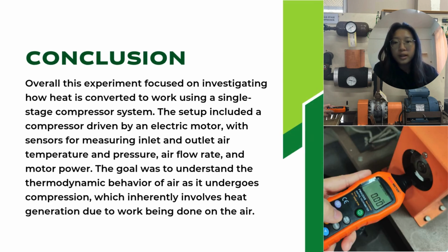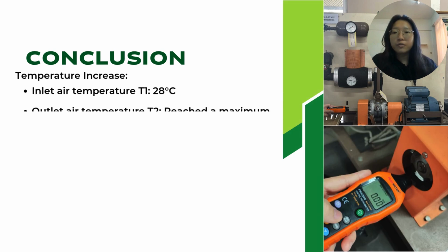Okay, so for the conclusion, overall this experiment focused on investigating how heat is converted to work using a single stage compressor system. The setup included a compressor driven by an electric motor with sensors for measuring inlet and outlet air temperature and pressure, airflow rate, and the motor power. The goal was to understand the thermodynamic behavior of air as it undergoes compression, which inherently involves heat generation due to the work being done on the air.